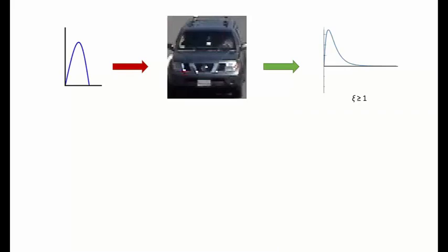Let me make this more clear by giving you an example. Suppose that you're working in a car manufacturing company and your boss says you to design a car that does not give any jerks at all while going over the speed breaker. You know that in order to manufacture such type of car, you need to have a suspension system, that is shock absorbers or shockers, that are capable of absorbing the shocks completely without giving any oscillations. That is, you would like to keep zeta close to 1 but greater than 1.